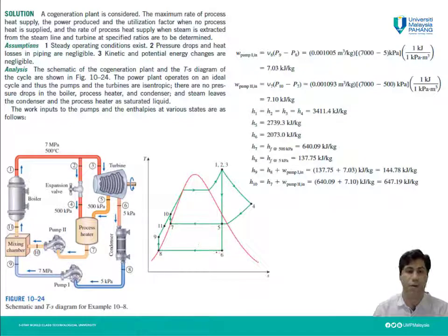And also for pump 2, again we have an isentropic process. And also in the turbine, which is 3 to 5, we have again an isentropic process. Then according to this graph, we should find the properties for the different states in the cycle.